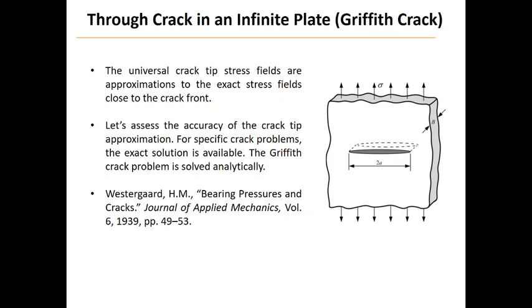At the same time, it is not correct all the way to the crack tip, because at the crack tip r goes to 0 and the solution goes to infinity. That's also not correct. So there's a region where this stress field and the K stress intensity factor are valid. We want to do at least some comparison or assessment of the accuracy of this approximation.